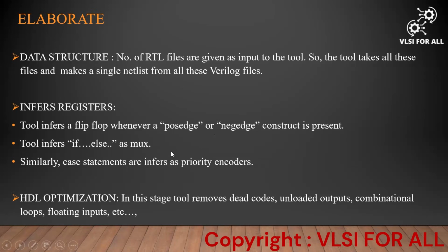And if the tool sees if-else statements, it will turn them into muxes. Wherever the if-else commands are read in that file, the tool will identify that a mux has to be inferred. Similarly, any case statements that are read will be taken as priority encoders.